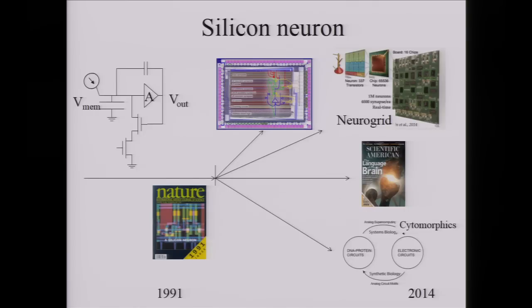And so the third area that I want to talk about is the silicon neuron. This is a circuit that Carver came up with called the axon Hillock circuit. It's a circuit that we still use nowadays in many of our chips because it's such a simple circuit. And it also, again, uses positive feedback. Right? So the circuit implements the integrate-and-fire mechanism of the neuron.